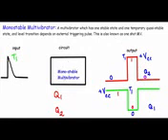A monostable multivibrator circuit will use two transistors, Q1 and Q2. The word mono means single. That means the monostable multivibrator will have a single stable state depending upon the transistor across which we are taking the output. If I take the output across the transistor Q1, then plus VCC will be its stable state, and if I take the output across transistor Q2, then 0 will be its stable state. In my circuit analysis, I will take the output across the transistor Q2. Therefore, from now on I will proceed with the transistor Q2.